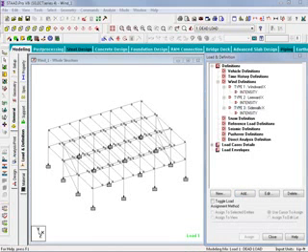Now for this particular building structure, I am complete with my wind load definitions for my global x-axis direction, and I'd also want to create the same types of wind loads in my global z direction, except of course my main building data would change. Now in STAAD.Pro, you are allowed to add as many wind definitions as are necessary for your particular building geometry and the particular directions that you need to consider wind for.